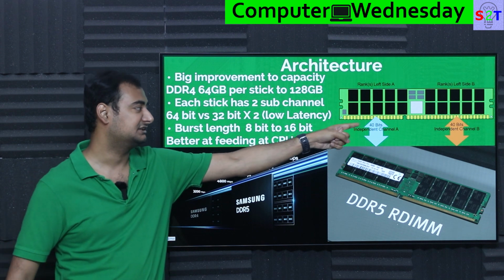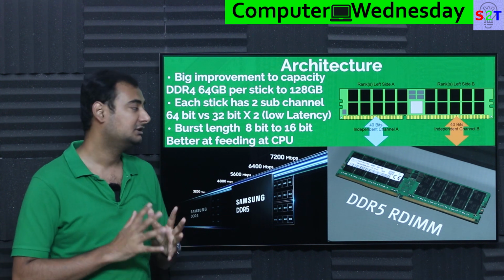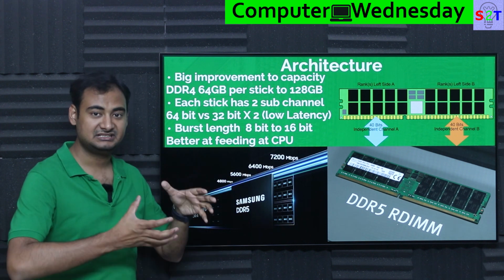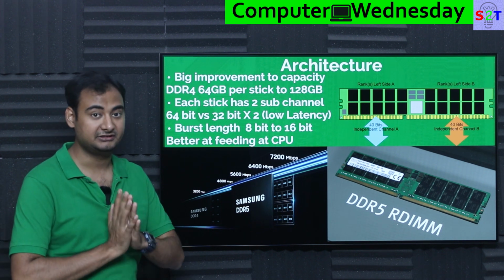Now you may notice why the heck this image says 40 bits when I'm saying it's 32-bit. Well, there are extra bits for error correction if the company wants to utilize that. Now, burst length has been upgraded significantly from 8-bit to 16-bit. That means basically the chunk of data is now much bigger. The benefit of this chunk of data is that the CPU can be fed very efficiently, very quickly.